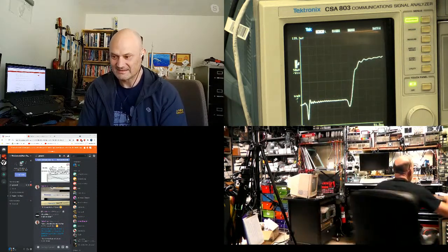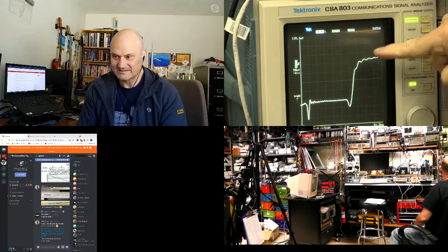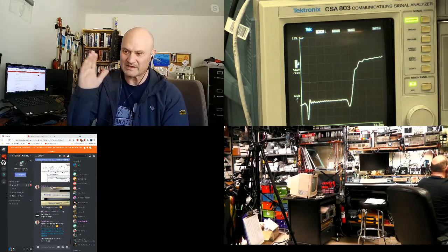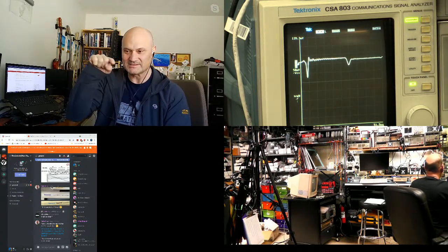Then it travels down again and comes back, and only a little more got absorbed, until eventually it comes out to be twice the voltage you sent. Those are also mini reflections on top of the reflections. There's a lot of back and forth, all adding up, and eventually it asymptotes to basically the peak voltage of your source.